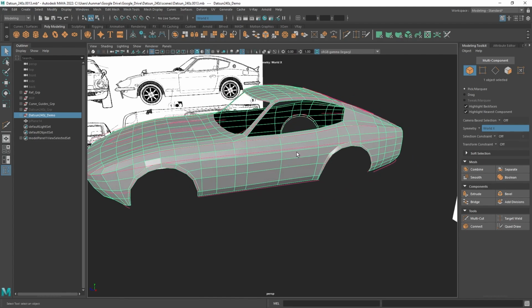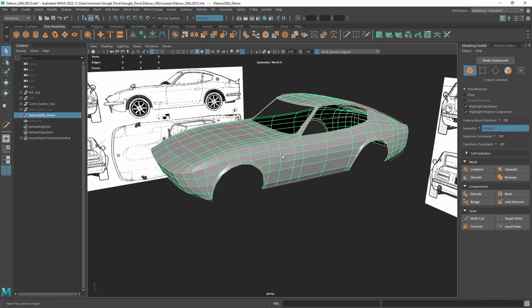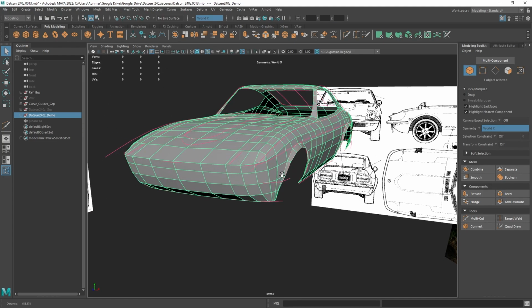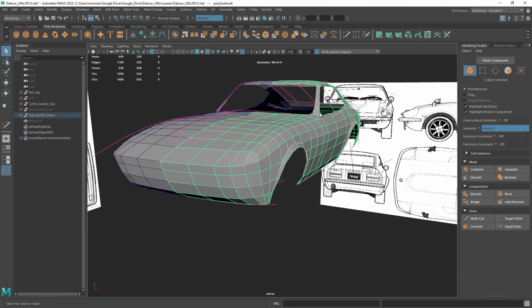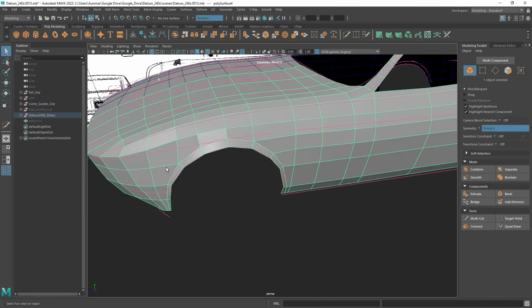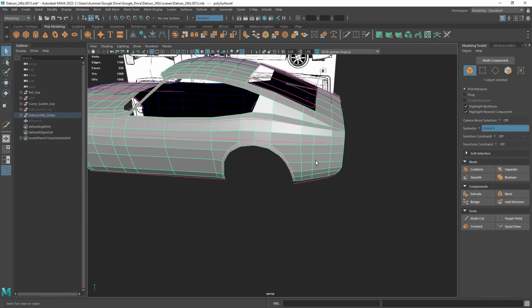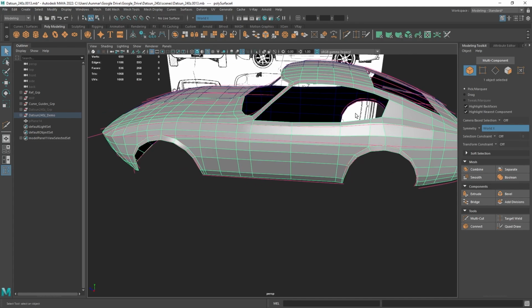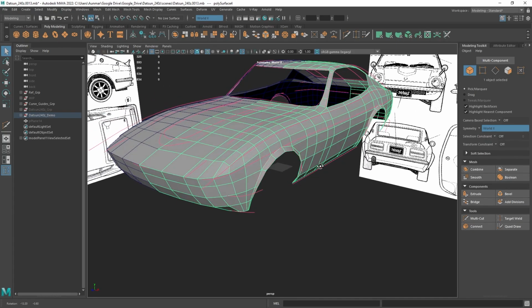All right. So to recap all the steps, we used planar modeling to work on actually building geometry. We focused on using the curves as guides and focusing on the body line of the vehicle. So you can see all my edges and everything line up to the body lines that I have here. We modeled in sections, so I focused on modeling the wheel well as a separate piece of geometry, did the rear part, the front face of the hood, and then just combined things and have matching topology. And then I focused right now just on the blockout and focusing just on the form. All right, so keep that in mind.